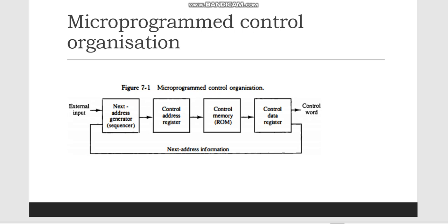The control function that specifies a micro-operation is a binary variable. When it is in one binary state, the corresponding micro-operation is executed. A control variable in the opposite binary state does not change the state of the registers in the system. The active state of a control variable may be either the 1 state or the 0 state, depending on the application. In a bus-organized system, the control signals that specify micro-operations are groups of bits that select the paths in multiplexers, decoders, and arithmetic logic units.